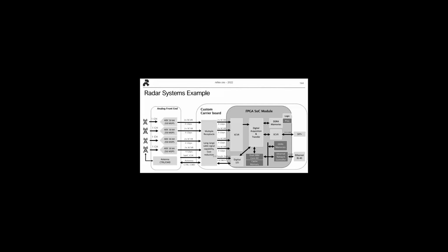All of that goes into an embedded system with a custom carrier board here. So you can develop your own analog front end, route that to the custom carrier board, and then go to the system on module based on FPGA, where you can fit the JESD IP based on the transceivers of the FPGA, using the power of your FPGA module with the system on module, so the processor inside and the memories, and you can do all the processing in a single solution.